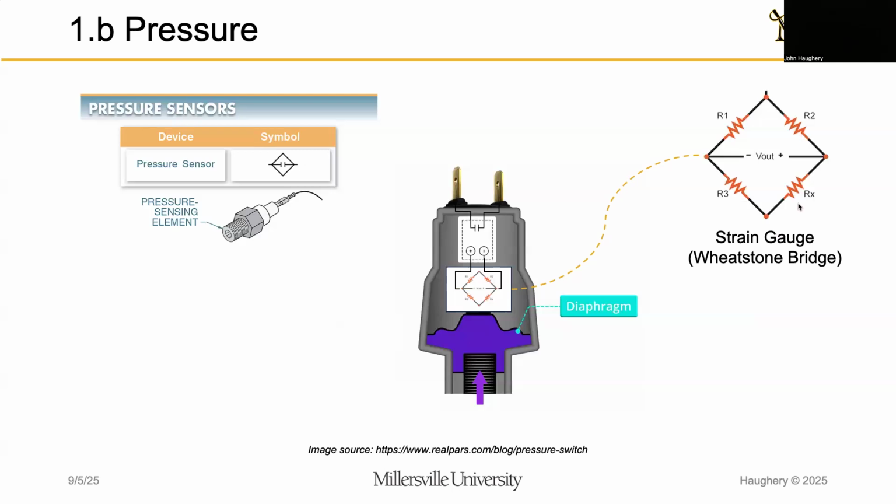As I push or pull on that strain gauge, one of the resistors will actually be flexing and it will change its resistance. And so the total balance of resistance will change, thus changing the voltage. And this is susceptible to very slight changes in resistance, so very minute changes. This is a typical arrangement that we use in a strain gauge. This voltage output then drives a solid state relay that has an output that gives us a signal or a contact that controls the load.